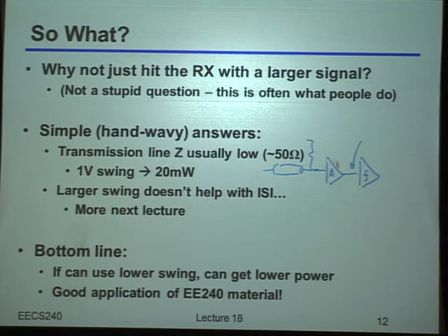So by the way, in general, this is just some very simple Class A or resistively loaded amplifier here. How much current does it take to get a certain gain and a certain bandwidth out of that amplifier? What's that equation we've been using over and over again? I believe it was back in homework number 2 and on the midterm. Yeah, okay, so you said it's the tail current times VDD, so that's indeed the power consumption. What is that tail current?